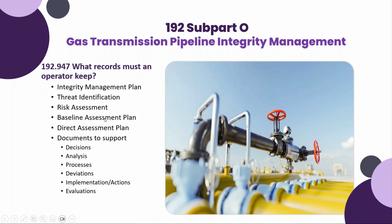Your baseline assessment plan has to be one of the key elements before you can even start integrity. You have to have a DA plan if you're going to use direct assessment, particularly for areas that are unpiggable, like crossover piping and things of this nature, small laterals, etc. And documents to support your decisions, even your telephone calls or team calls. They should be documented. Decisions, analysis, the processes, any deviations from it, implementations and actions and evaluations.